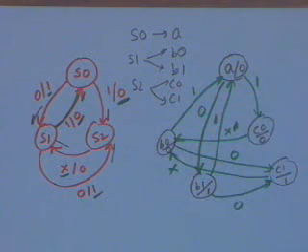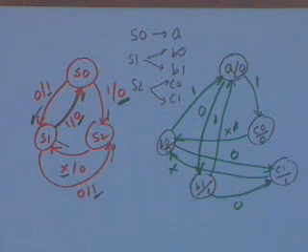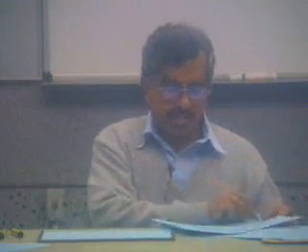So I have checked both C0, C1, B0, B1 and A, these 5 states, and this is an equivalent Moore machine. It is very difficult to just draw the timing diagram and make sure that the output is delayed by 1 clock cycle, because the way we have performed the transformations ensures that. Let us look at the other problem that is a little more difficult to directly see.